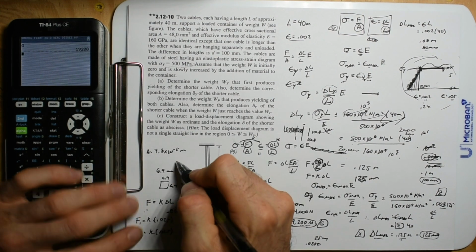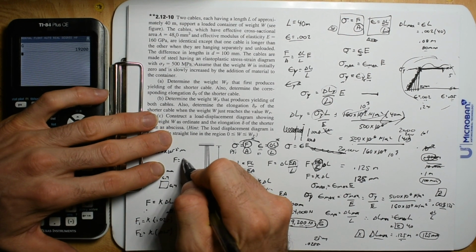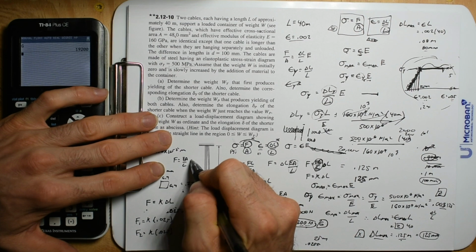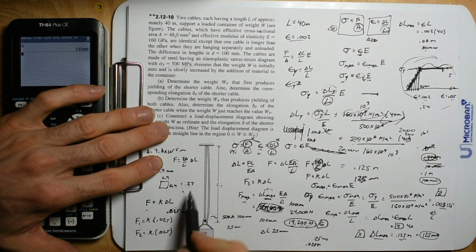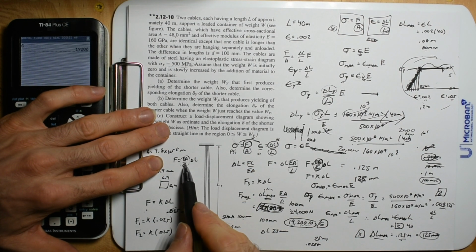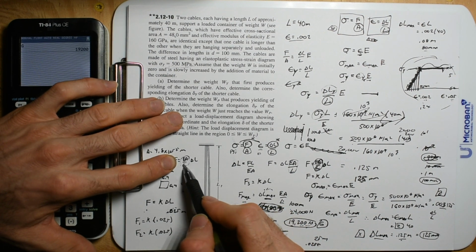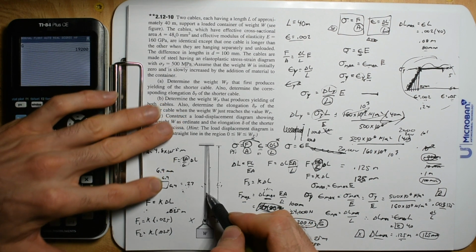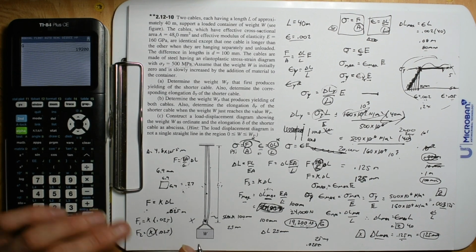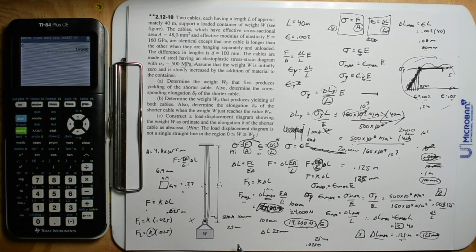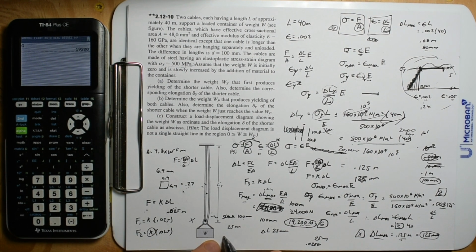Guess what? Force is equal to EA divided by L. You just have this kind of memorized because that's K. And what is K? It's a function of a constant and then the area that we chose and the length. Both of these are identical, so K is going to be identical for both of them. But let's just solve it for one, just so we don't get messed up.